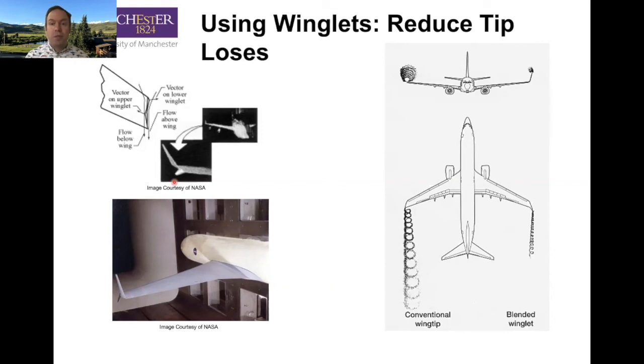You normally see upward facing winglets, and those are really useful because they're less likely to strike the ground. Unfortunately, they're actually the less efficient. This downward winglet you see here actually generates a much better return for the same area and same weight as an upward winglet. So you're seeing that on the new 737s that are being retrofitted, the Next Gens, and on the 737 MAXs. The consequence, of course, is that this is more likely to be damaged in a wingtip strike.